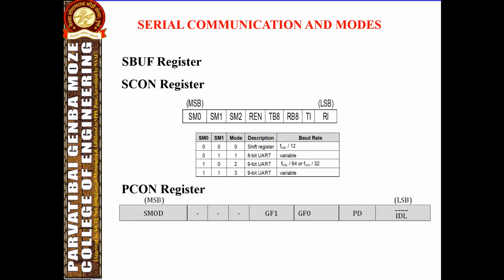The 8051 is a serial data communication circuit which uses a register in the SFR. SFR means special function register, called SBUF, to hold the data. The SFR register SCON controls the data communication, and the SFR register PCON along with timer 1 control the data rates.